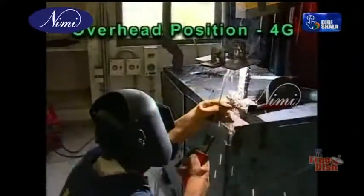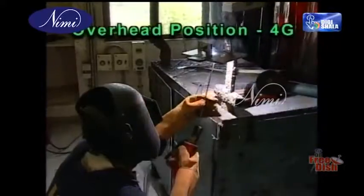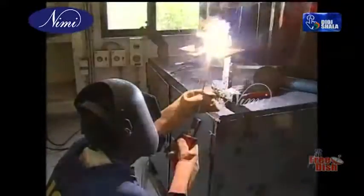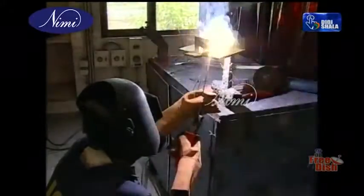Overhead position. In overhead position, as the name indicates, the welding object is placed over the head of the welder and, in reverse to flat welding, the electrode is placed vertically upwards during welding.